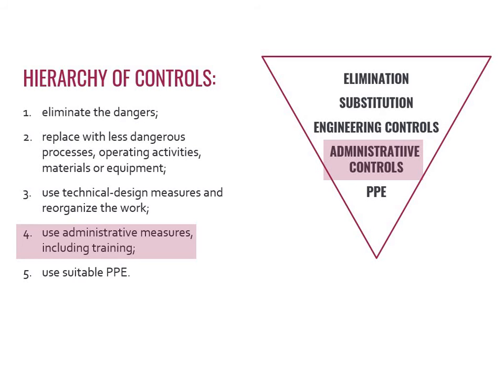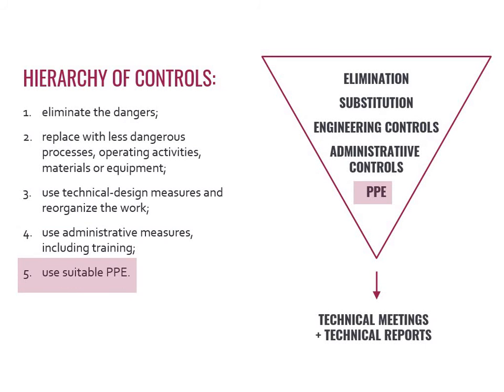If it's not possible, let's move to step 4, administrative control. The fourth way would be giving workers specific training to teach them how to operate in order to spend as little time as possible near the noisy machines. And finally, the fifth step, PPE. The final resort that has to be done only after the ones before is giving PPE to all your workers.